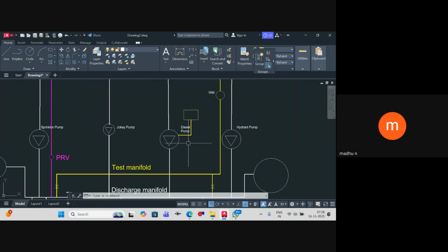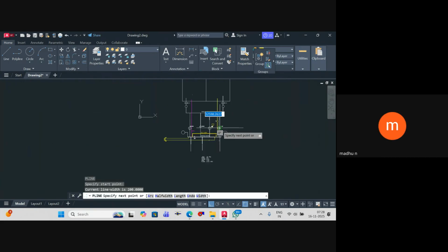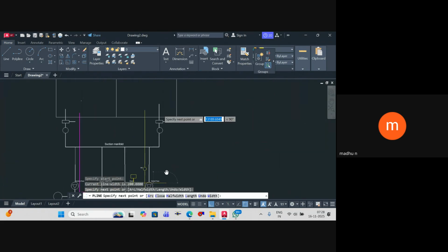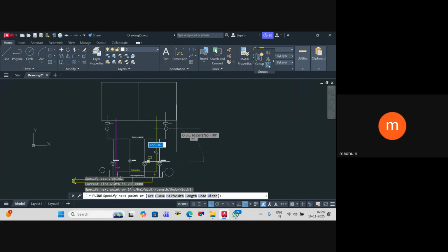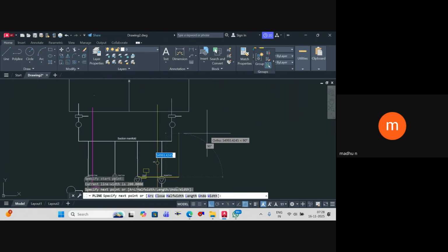The diesel engine exhaust also you have to place. So from the diesel engine, you will take the exhaust and keep it externally. You'll take a silencer with that particular pipe, and generally it will be 80 mm dia or 100 mm dia. Worst case is 150 max. So that particular pipe you take out and then you give it outside. Even if you have anything, about 3 meters.